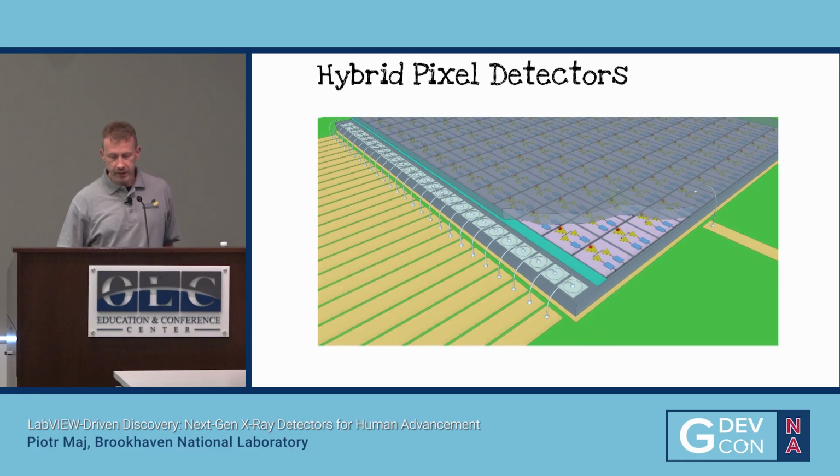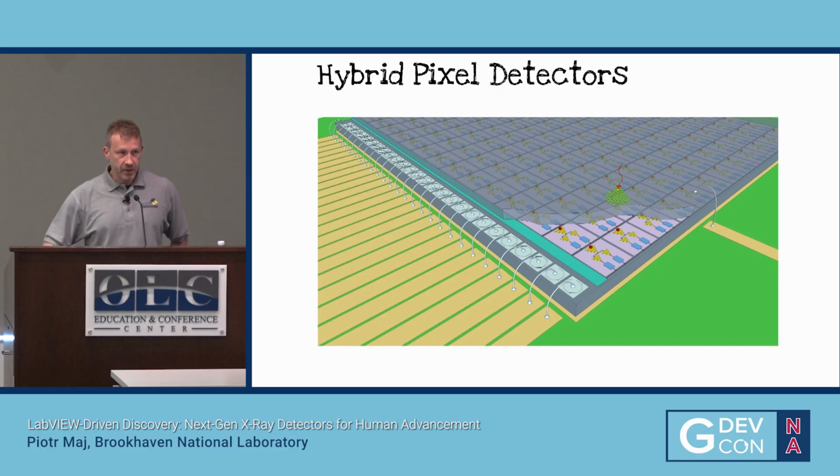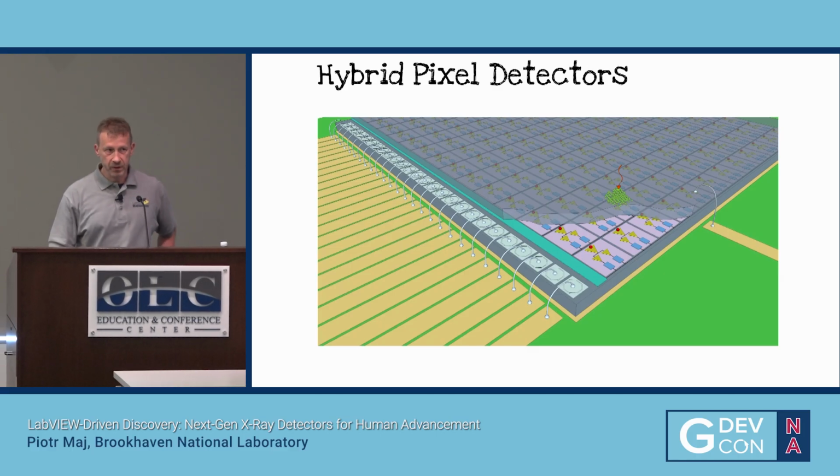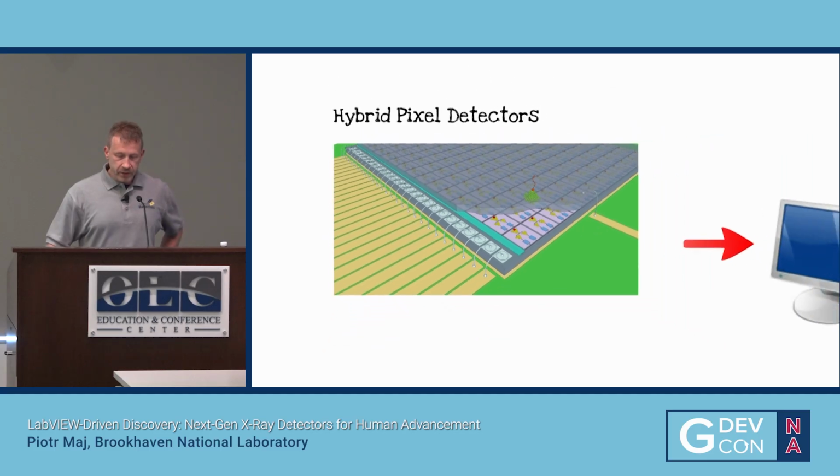power and data. When the X-ray photon hits the sensor, we want to collect this cloud of charge. The cloud of charge, roughly 2,000 electrons, is our input signal, the current pulse. We have to measure it. There's no device you can just buy; you have to implement it, build it. And then we read the data into the PC.